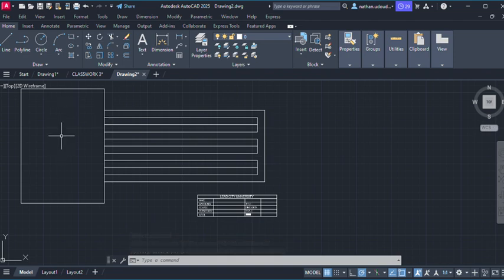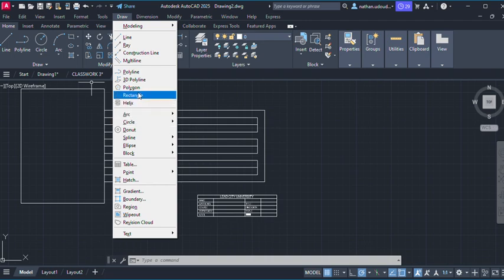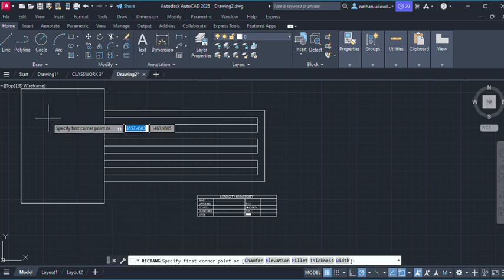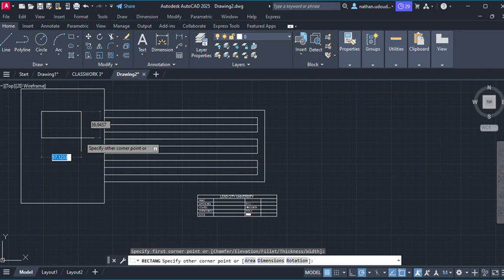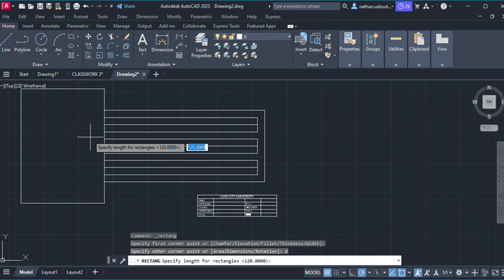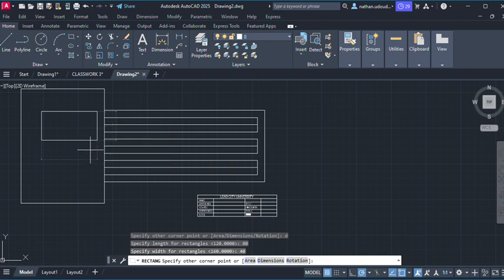So now let's draw the inner rectangle. So you can just come here, take your draw toolbar, rectangle. The length is what? 80, while the breadth is 40. So you take your starting point. So you take your dimension, which is D, enter. So the length is 80, you type 80, enter. The breadth is 40, 40, enter. Then you now left click.